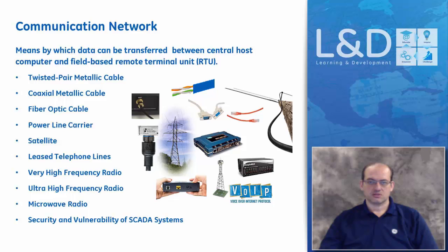The physical security of this communication is very high, since the power line carrier equipment is located within the utility property, and as long as the utility property is protected, the communication is protected from hacking or external access. So security plays a big role when we decide which communication media we're going to use in our SCADA planning.